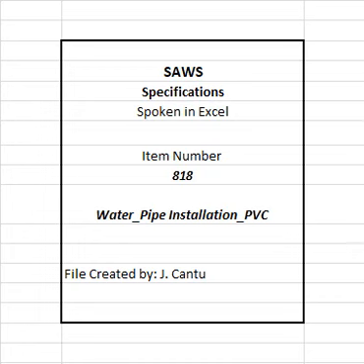7. PVC, C900, and C909 pipe shall be field cut using a power saw with a steel blade or abrasive disc, depending on the size of pipe. 8. If a bevel is needed after field cutting, it should be in accordance with the latest applicable recommendations of Uni-Bell or ASTM/AWWA standards. Such work will be subject to approval by the inspector.